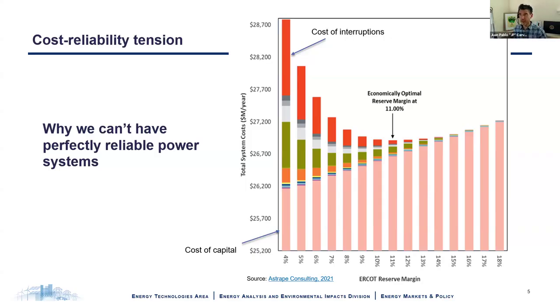And it's also true that these planning reserve margins can be, and are being, set at the seasonal level, because again, the winter and summer reserve margins might be very different depending on what resources are supporting the grid in those seasons. Places like MISO that have 4 seasons are already seeing different decompositions of portfolios showing up in winter and summer, and they're conducting auctions for winter and summer to meet load in those different seasons. Great.